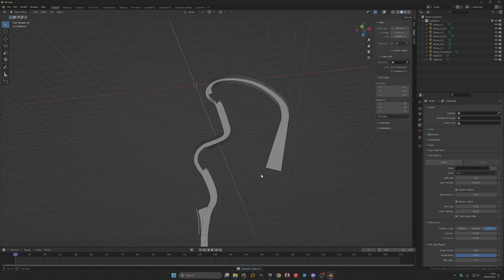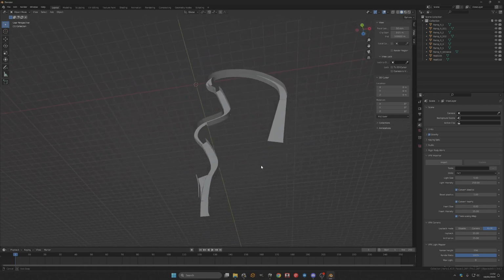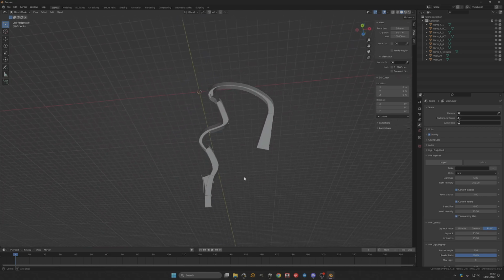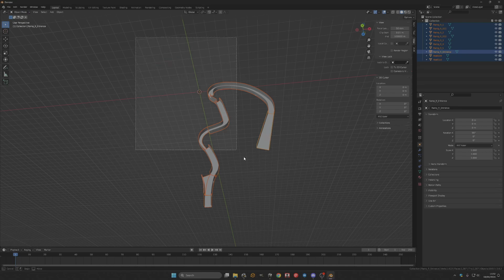Now, this whole thing we're going to attempt to make as a ramp. So select the whole thing, select everything here. Right click on it. You have to click one of them. So you select the whole thing and then highlight one of them and then click join. Control J or join. And that makes them all one primitive now. They're all one object, rather than before when they were all separate ones.